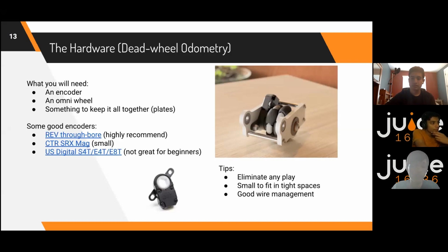In order to do this, we use suspension with rubber bands and force the wheels onto the ground, so that no matter if our robot climbed onto something or hit another robot, the wheels are always on the ground and always tracking.